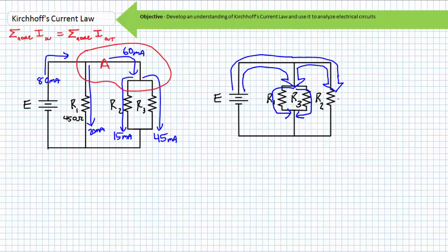Regardless the arrangement of exits, overpasses, turns, roundabouts, and jug handles, all incoming current must travel the single highway into this node, and all incoming current must leave it. More current will travel through paths with less opposition. Less current will travel through paths with more opposition. Equally relevant is the rejoining of individual paths at the bottom node. Regardless of the physical configuration, any parallel circuit of three resistors yields the same KCL equation. Incoming current is I1 plus I2 plus I3, and outgoing current is Is.